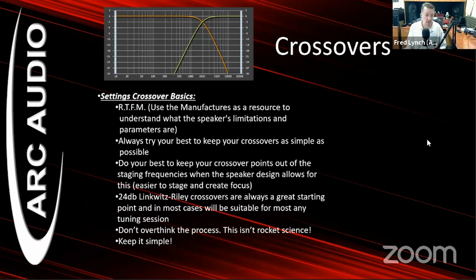Setting crossovers. Like I say, not going to get into a lot. Read the manual. Learn more about the speakers that you're using. Talk with the manufacturers to find out what the limitations are. Keep them simple. Keep those crossover points out of the staging frequencies. And also another great tool, have everything start with the 24 dB Linkwitz Riley. It's probably one of the smoothest and best starting places for any tuning session. And it's not rocket science. Don't overthink the process and keep it simple.